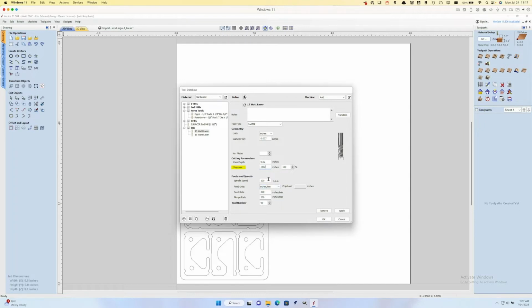What we're doing in Mach is we are taking a router toolpath, and in Mach it's getting changed into a laser toolpath. So that means programs like Aspire, VCarve, Cut2D, Cut2D Desktop, Fusion 360, and other CAM programs can send regular routing toolpaths, and we will change them in Mach for you to a laser toolpath. And what we're doing is we're setting spindle speed to laser power. So if you set your spindle speed, quote unquote, for laser at 100 RPM, that's going to operate the laser at 100% power. If you set this at 50 RPM, this would operate the laser at 50% power.